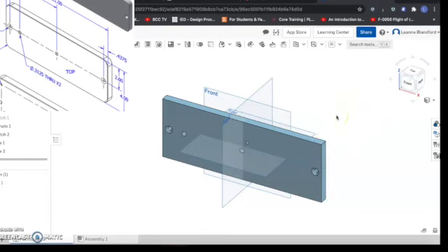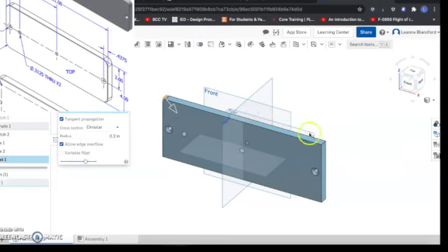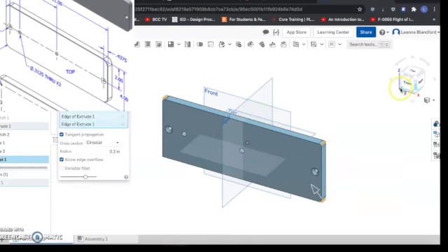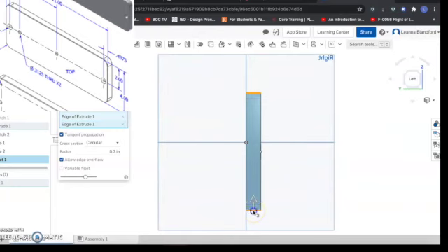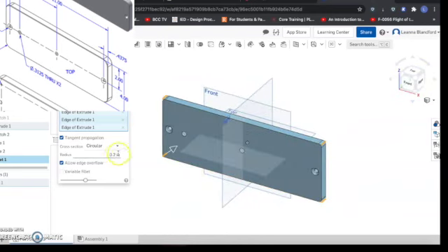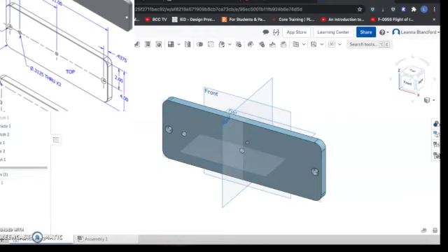So I'm going to use the fillet as a feature. I need to fillet this to a 0.5 radius on all 4 corners. So I'm going to choose fillet, and I'm going to very carefully select the 4 lines that make up these corners. And I'm going to rotate over here and select this one. I can then rotate back using my view cube, and this has to go to 0.5. I'm going to hit enter so it previews it, and I'm going to hit the green check mark.